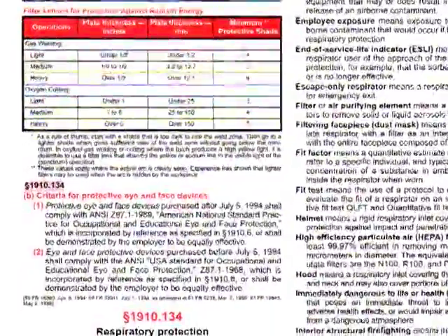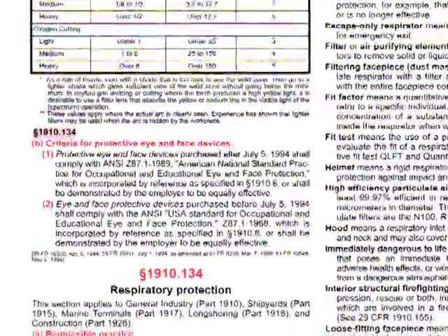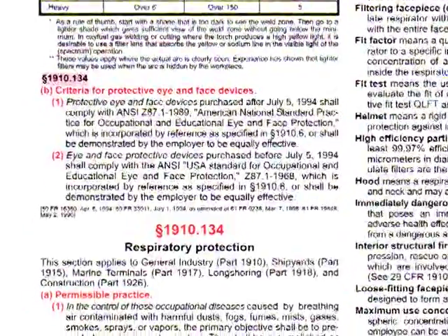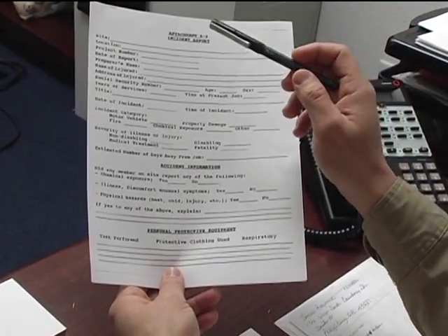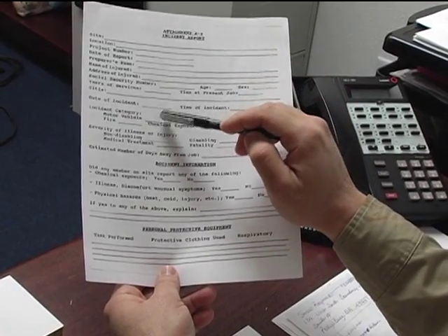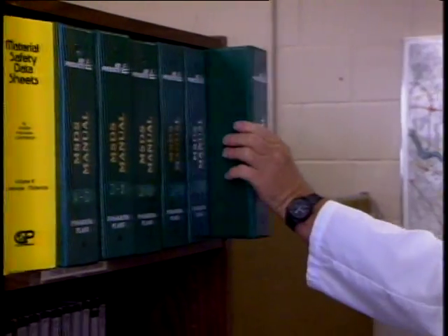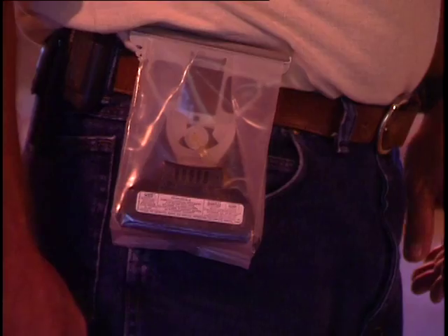The OSHA standard applies to all occupational exposures to contaminated air where an employee is exposed to a hazardous level of an airborne contaminant. You are required by the employer to wear a respirator, or you are permitted to wear a respirator. Employers have 4 duties that OSHA has imposed on them. First, they should use engineering and administrative controls where feasible to control the hazard.